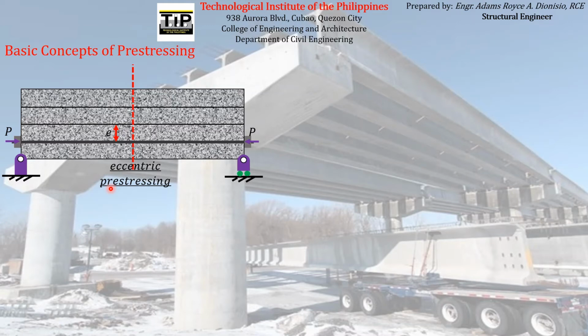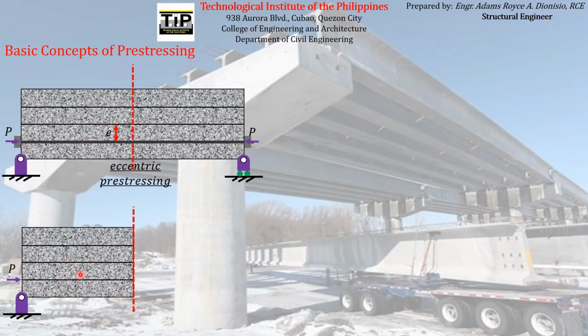So now, if we want to investigate what will be the effect if we have moved the pre-stressing reinforcement from the centroid or from the longitudinal axis to a certain distance E, we just have to again cut the concrete beam, put a cutting plane there, and divide the concrete beam into two sections or two segments, left and right segment. Again, we will just use the left segment. So the free body diagram will look something like this. So again, to balance this force, the compressive force coming from the pre-stressing reinforcement, there must be a force that must counteract that. That will come out when we cut the concrete beam.